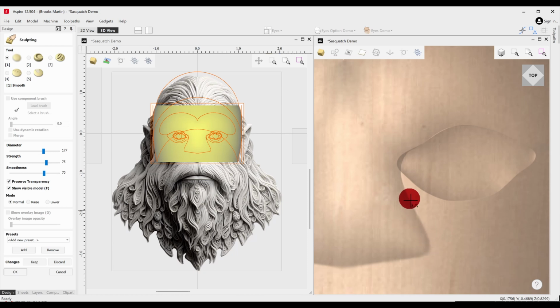If you selected two components, it would bake them together, so it was doing the same thing, but you wouldn't have the ability to go back and redo it, because it just takes those components and creates that one composite out of that component, and that component is gone. So make a copy, and then what we did was bake it by using the copy routine.